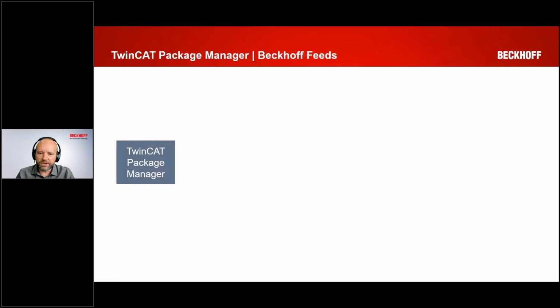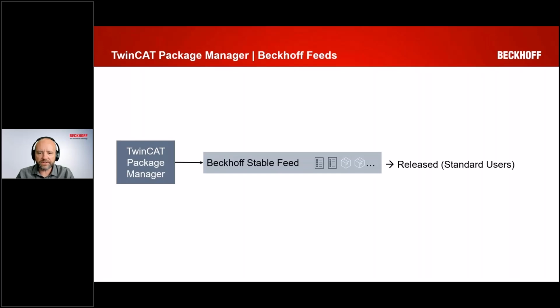So an important topic to also define here is where you're going to get your packages and workloads from. So that's what we use the Beckhoff feeds for. So your package manager shown off here to the left would connect to the Beckhoff stable feed. So the stable feed is the most common feed. It's the one that 90–95% of customers will use, and maybe the only one they will use. So it contains our production software. So anything that is released by Beckhoff that's supported on production machines is going to be in this feed. So this is the equivalent, if you've been a Beckhoff customer for a while, this is the equivalent of when it releases on the website or whatever.